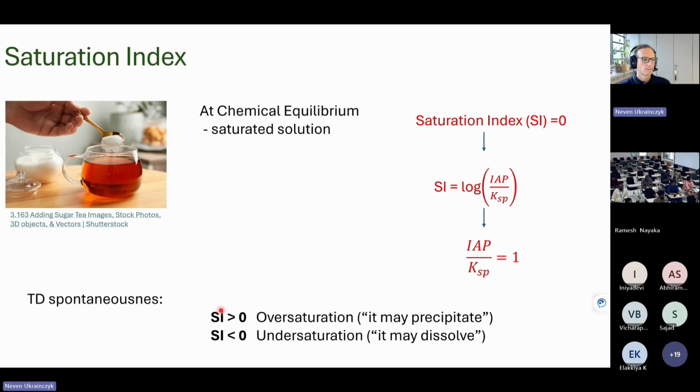And this is what happens with leaching. If you have C-S-H products and you start to leach out, you are basically undersaturating the solution, and you are dissolving the portlandite first and then the C-S-H next. So you are leaching out the C-S-H phases, which is even more pronounced with acid attack, because again you have this common ion effect.